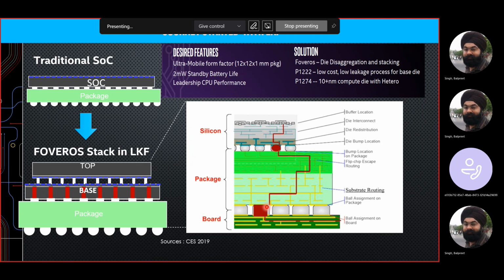Not just that. In a monolithic die, let's say you take a 100 micron square area. Let's say bump pitch, you take about 100 micron. So you can keep your 4 bumps that are only supporting the one die's power supply need. Now, when I have a first floor and ground floor, the same number of bumps need to support both the needs of the ground floor and the first floor. So physical real estate actually has reduced